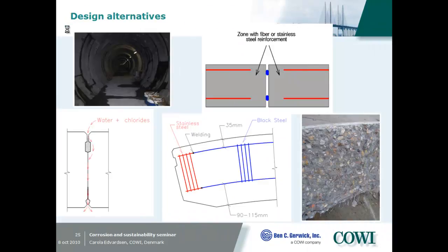This is because a bored tunnel is never watertight. There will always be some water coming in through the joints. I never saw a bored tunnel which is completely watertight. And therefore we have a risk of chloride accumulation inside the tunnel, just beside the joints.